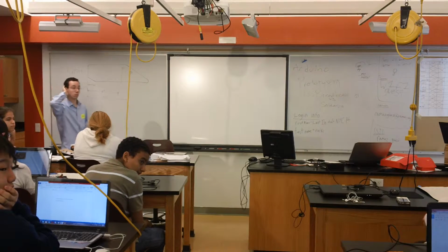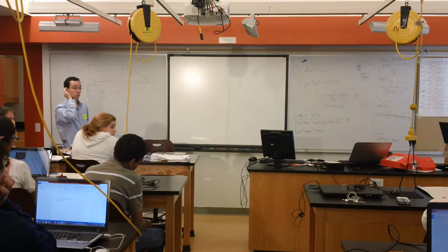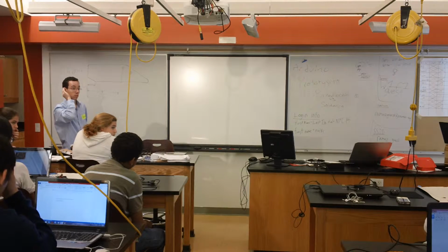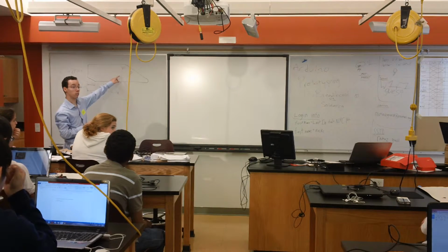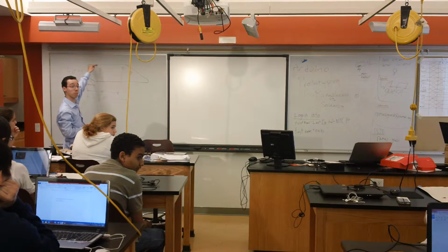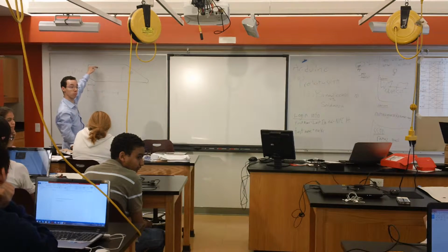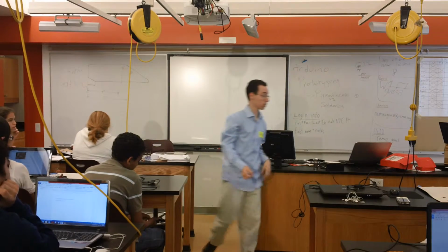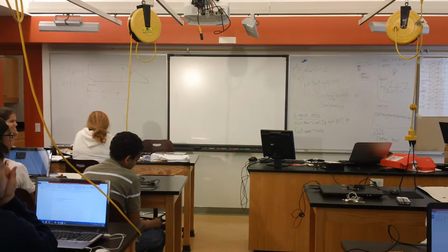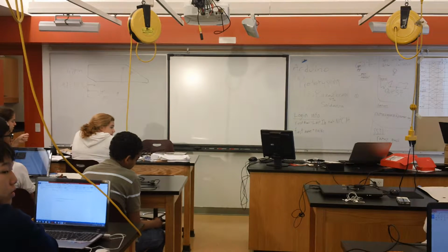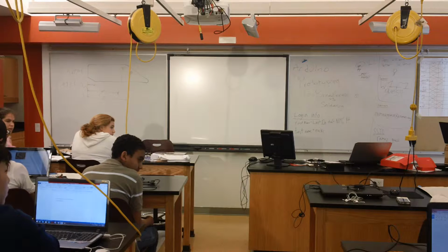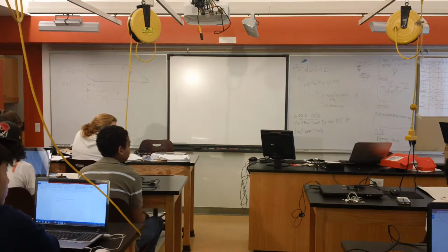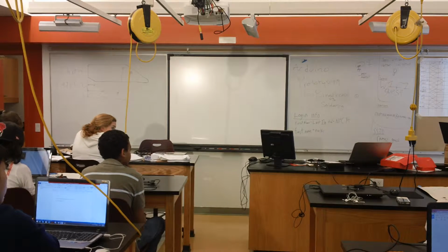So in datum dimensioning, in order to figure out how far away the hole is from the bottom edge, would you give it from the bottom? Or would that be considered chaining, and rather you just give the distance from your original point? So if you're going to give a dimension, from where that top hole is, would you give it from the bottom edge, or would you give it from your original point? From the bottom, oh, I see, yeah, I'll show you.